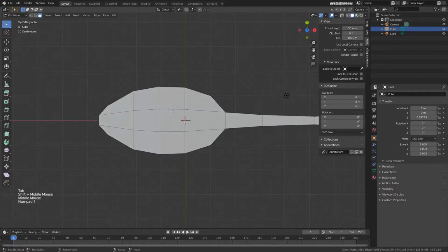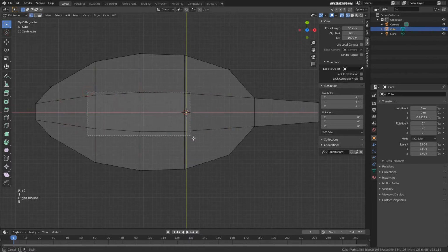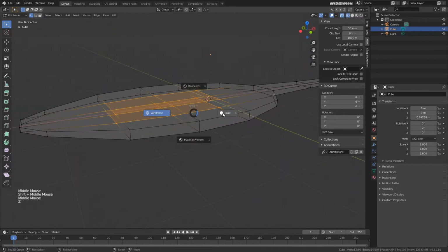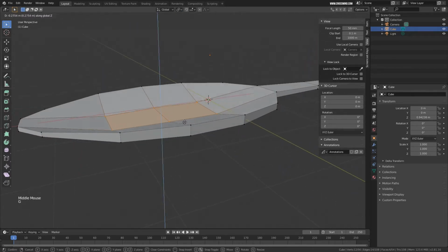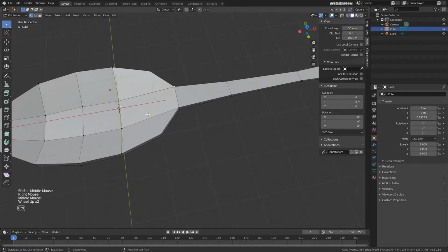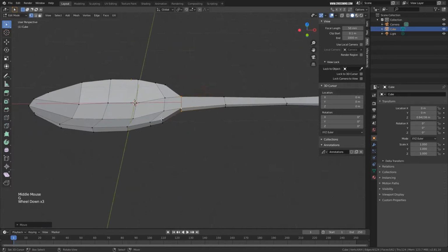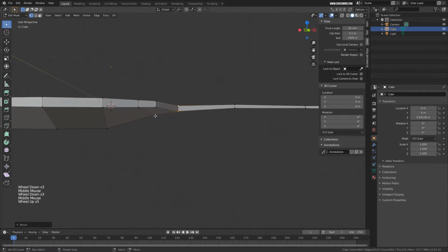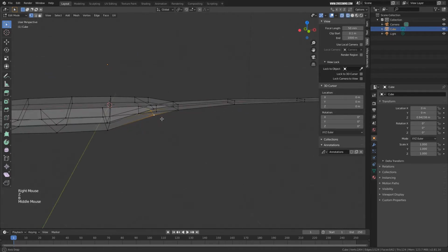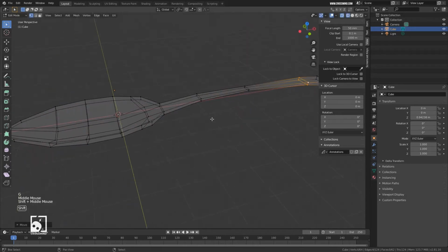So I'll go to the wire mesh again, and I'll select all these and go to the vertex mode. I'll select all these faces or vertices and move them in the Z direction like this. Alright, and if you'd like, you can add one more subdivision over here to smooth it out. Maybe you can select this one. It's something like a bend, okay. And select this, you know, this shape of the spoon, and this is just to clear out the concept.